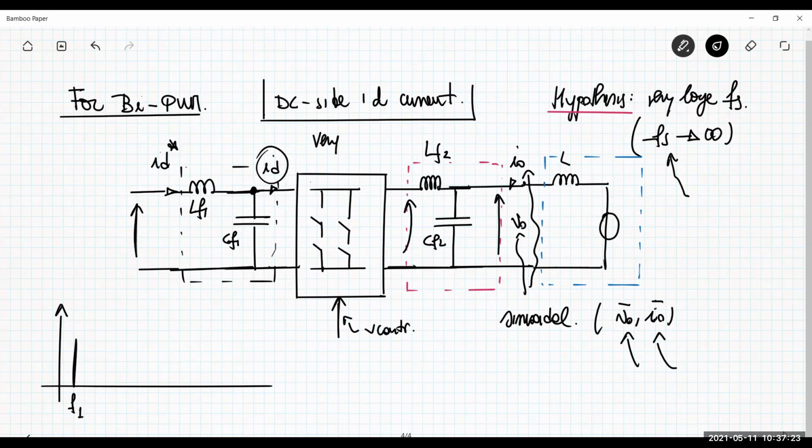Then you have something around the first harmonic of the frequency of switch, which is very large. So basically you have a very large frequency space in which you have just F1. This filter here is something that you want to use for isolating F1 with respect to all the higher order harmonics, in order to have at the output just the sinusoidal behavior. You want to mitigate the effect of the switching frequency and then all the subharmonics,